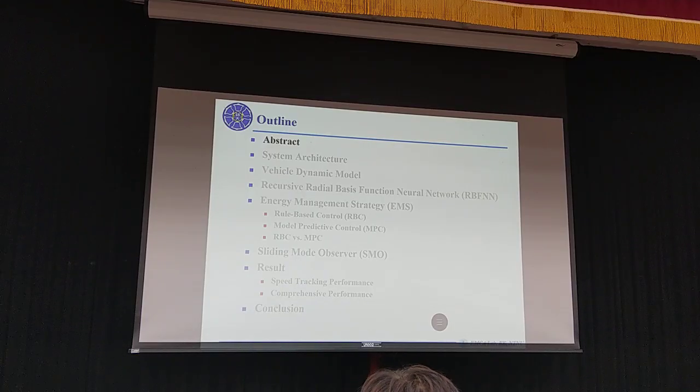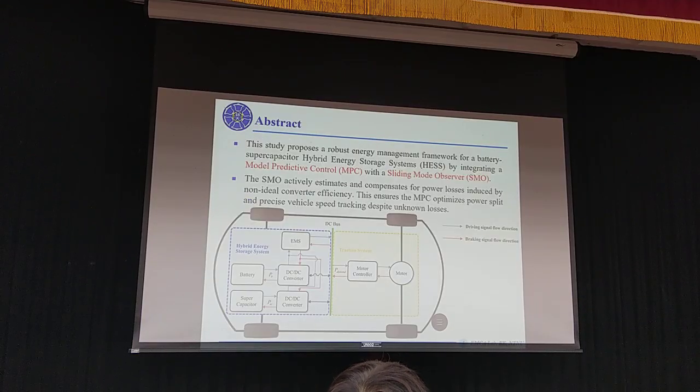Now let's move on to the abstract. The study focused on the battery and supercapacitor HESS. Traditional methods often ignore converter efficiency, which causes power gaps and speed drops. To solve this, we combine MPC with the sliding mode observer. The SMO estimates and compensates for the power losses in real time. This ensures precise speed tracking and optimal power split, even under unknown disturbance.